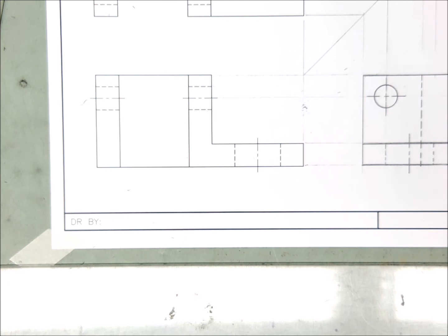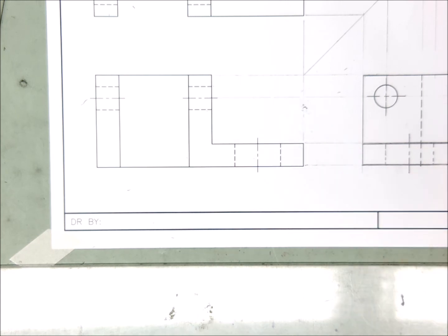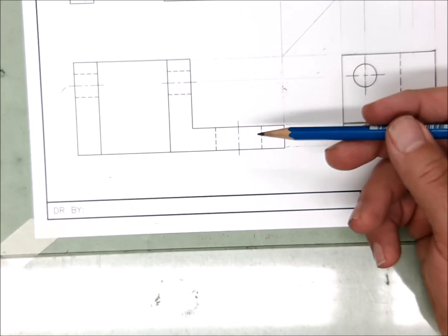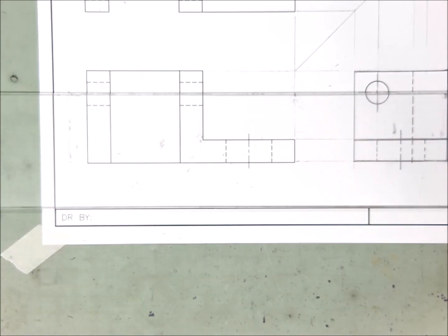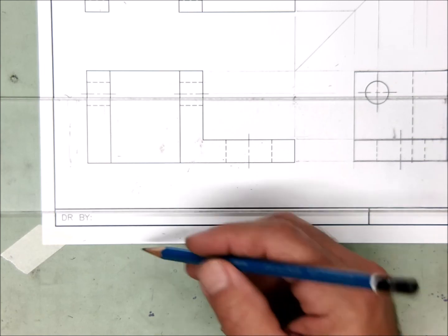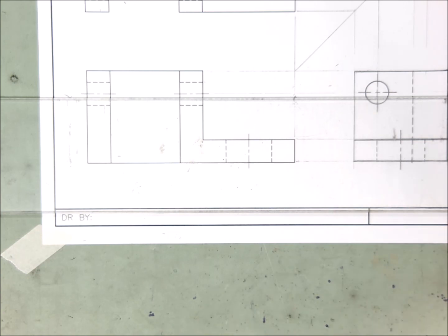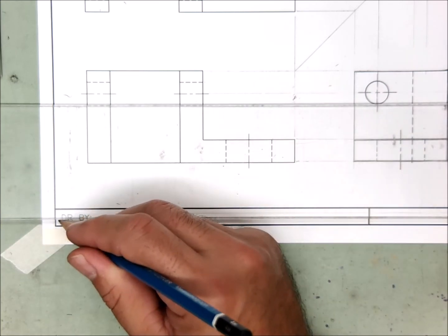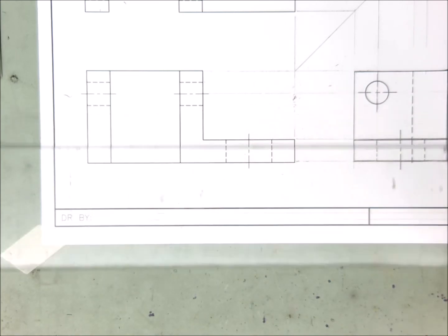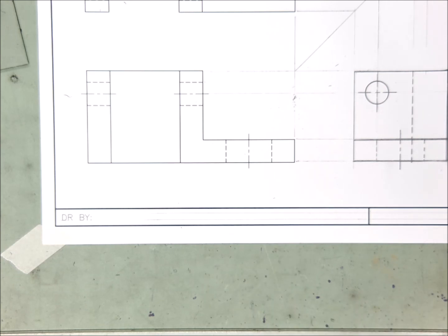Either with your light blue pencil sharpened to a very sharp point, or maybe with one of those 4H wood pencils. If you don't have either of those, then your 0.5 mechanical pencil with a very soft touch. Very soft touch. Draw two very light guidelines above and below the lettering for drawn by. Right, and those two light guidelines will be what you use for your lettering when it's time to put your name on this.